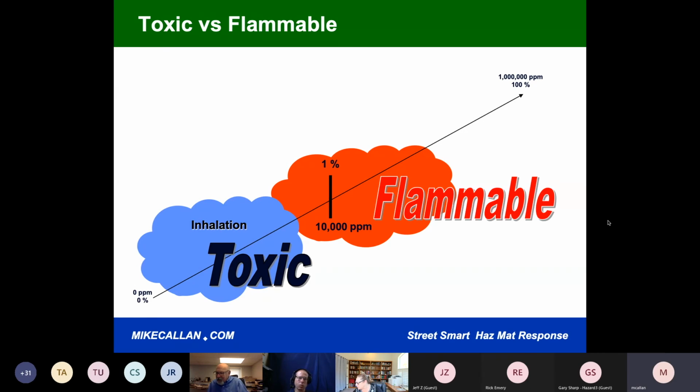There's only 4 chemicals that this doesn't work for. Methane, ethane, acetylene, and I've forgotten the 4th one. Methane, or natural gas, that's how I look at it. Hydrogen, that's it, hydrogen. Everything else is going to be toxic. Those are only asphyxiants. I can guarantee you if it's a flammable liquid, it's toxic. There's no doubt about it. It's got a PEL, and if that concentration rises and we keep getting closer to the leak, give me one more click.